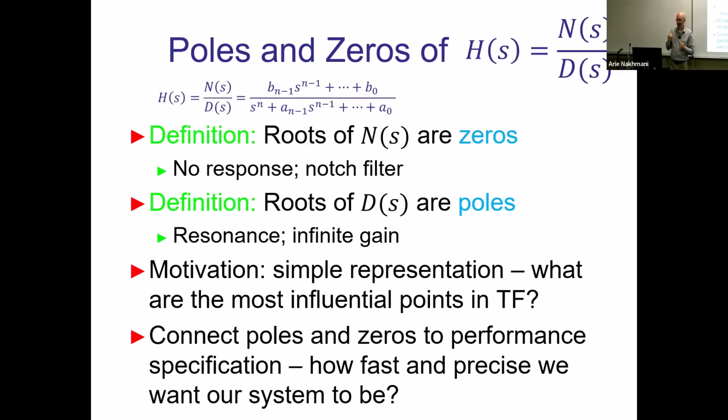Right. So I guess we only really are plotting this in the Bode sense where you're getting zero or pole. Yes. Okay. I mean, you have also phase, but phase of zero doesn't matter, and phase of infinity also doesn't matter.